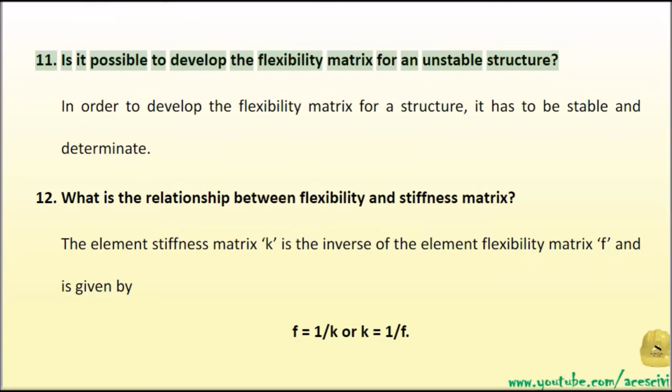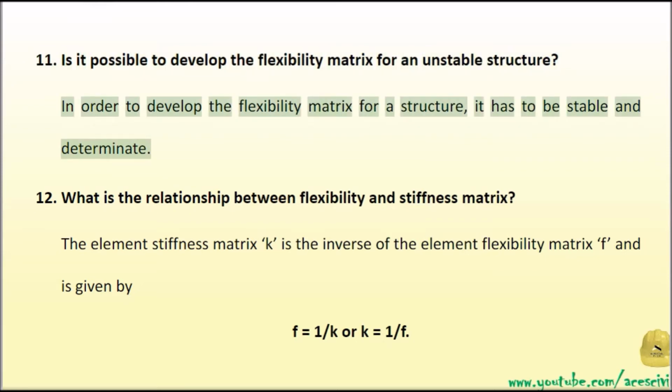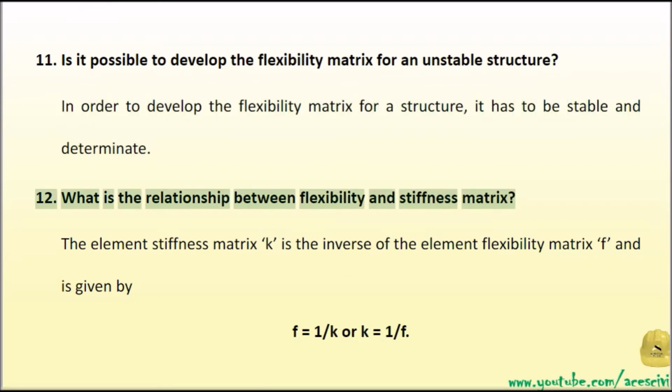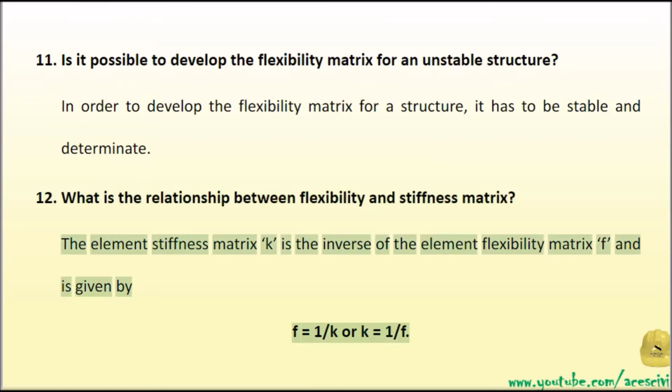Is it possible to develop the flexibility matrix for an unstable structure? In order to develop the flexibility matrix for a structure, it has to be stable and determinate. What is the relationship between the flexibility and stiffness matrix? The element stiffness matrix K is the inverse of the element flexibility matrix F, given by F equals 1/K or K equals 1/F.